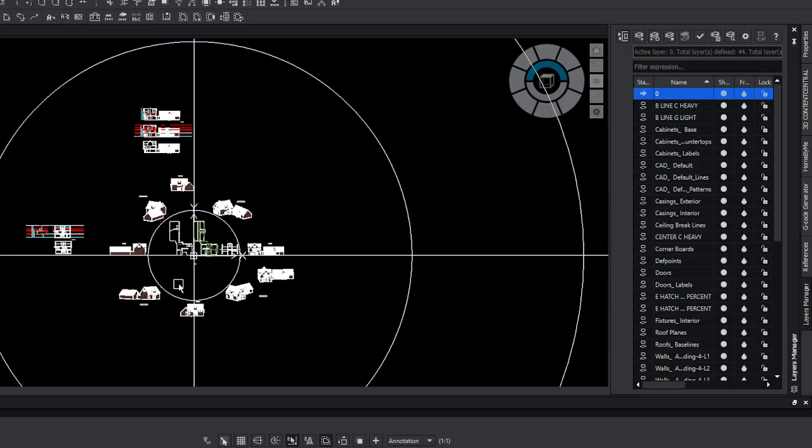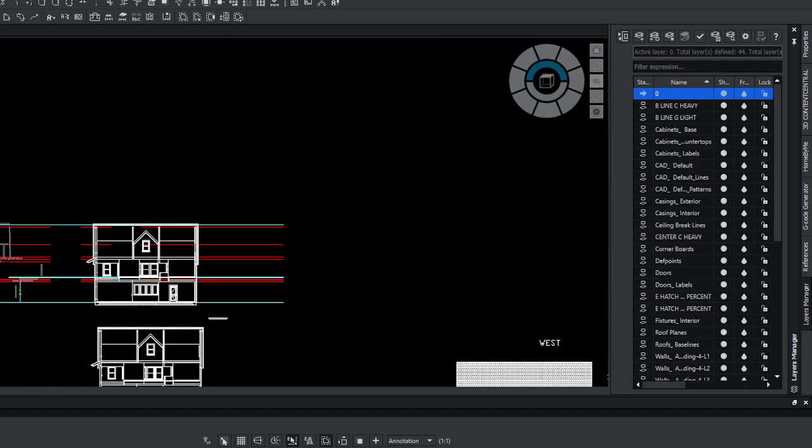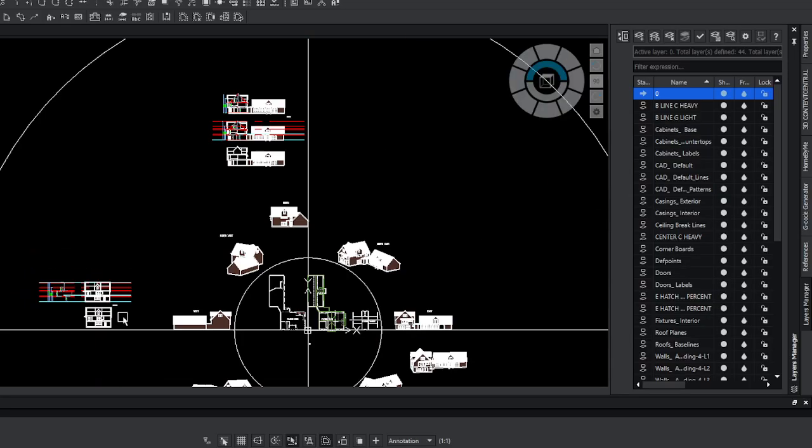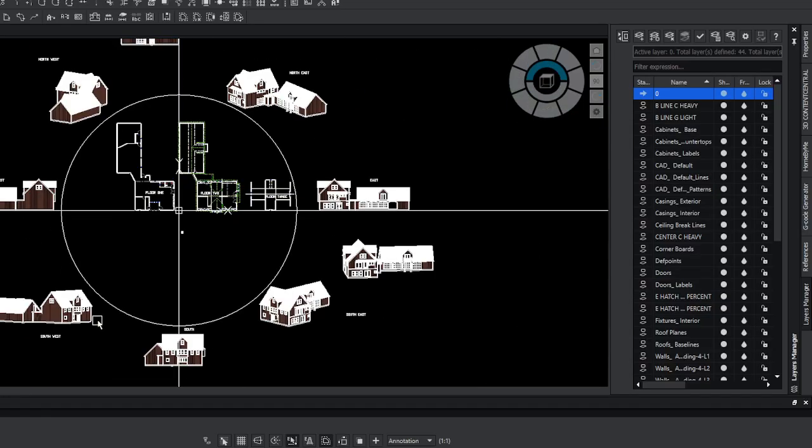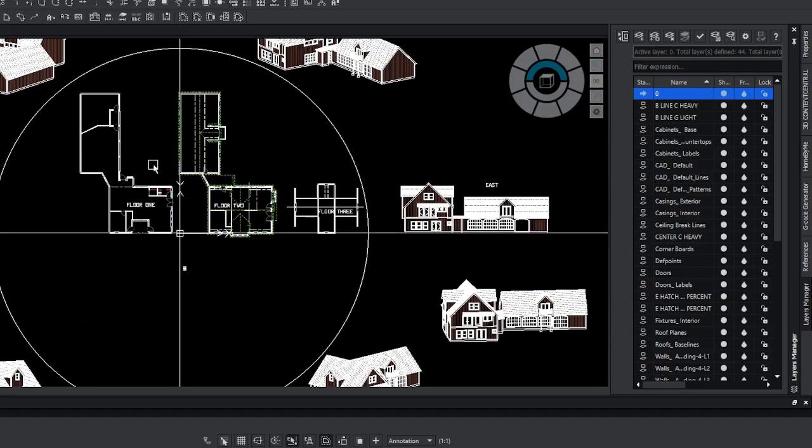If I was going to take this project further, then I would take each of these sections and clean them up a little bit, make sure that they scale. In other words, I would take these dimensions from the sections, and I would make sure they match the elevations, and then I would sheet all of this for the as-built part of the project. Then if this was an addition, I would take the direction from the contractor or client or whoever, and I would turn this into an addition.